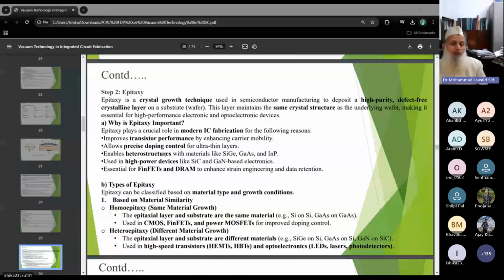Yeah, epitaxial growth, especially in integrated circuits using BJT. There the epitaxial growth is very important. If we fabricate the BJT directly on the wafer, then there is the problem of collector resistance, which will affect the gain and various other parameters.